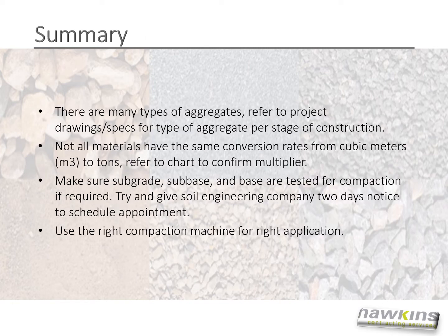In summary, there are many types of aggregates. Refer to project drawings and specs for type of aggregate per stage of construction. Not all materials have the same conversion rates from cubic meters to tons, so please refer to the chart to confirm multiplier. Make sure subgrade, subbase, and base are tested for compaction if required. Try and give soil engineering companies 2 days notice to schedule an appointment. And use the right compaction machine for the right application.